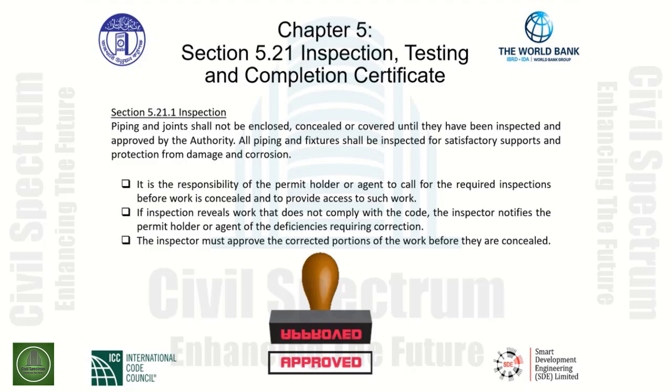This is important so we can verify the materials have been used that are proper. The materials have been used that have been approved and that are in this code. The fittings have been made up according to proper installation standards. The correct size of pipes according to the construction documents is what we look for out in the field. And the bedding as well as the depth of the pipe accordingly.